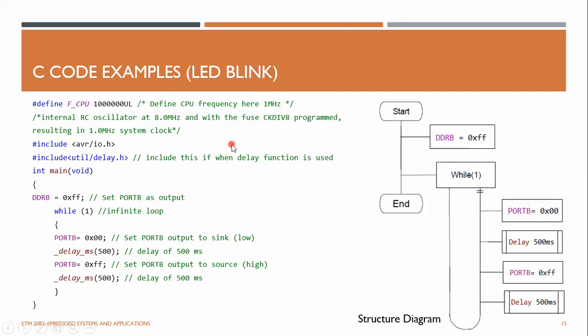Any programmer will start with a simple LED blinky code. So, to blink an LED with a delay of 500 milliseconds, you can write this code in Atmel Studio. Go and open the Atmel Studio and write this code. Before that, I will explain what this code means.